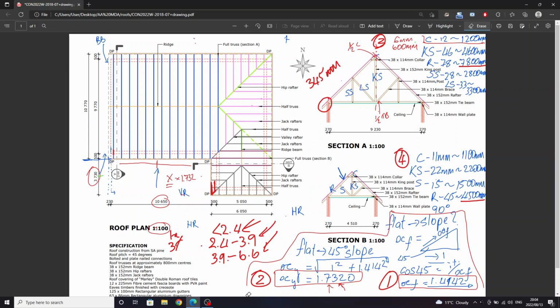You just take, so for your roof covering, you take that side, you multiply it by your gable end, and remember at the end of that huge description for a roof tile, you need to apply your factor, which I've put down here. And remember, don't use this factor. That's for your rafter, your hip rafters. So you must use this factor for your standard rafters. And at the end of that giant tile description, you add times 1.4142, turns the whole thing into slope, like this.